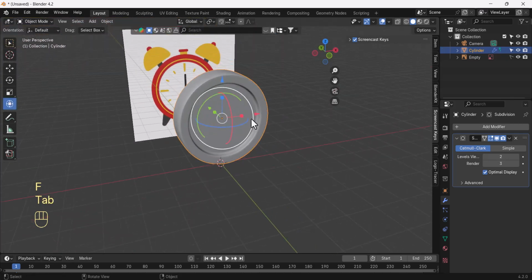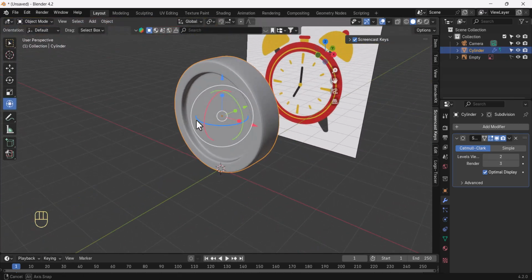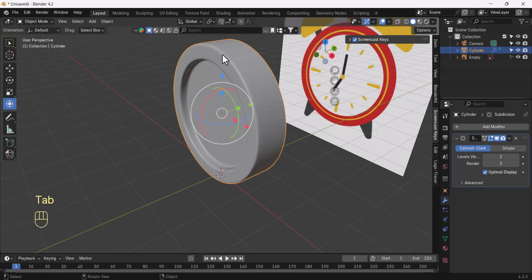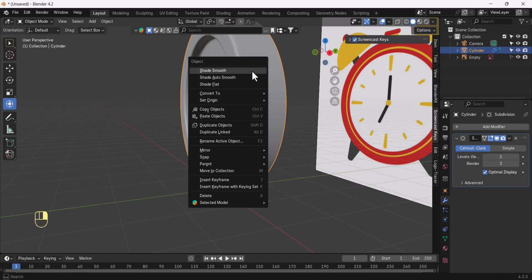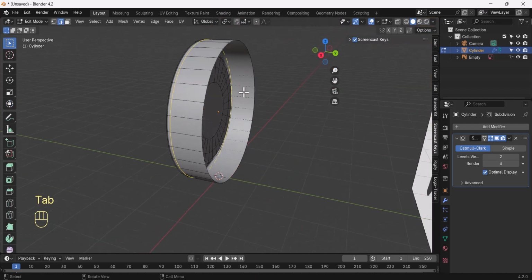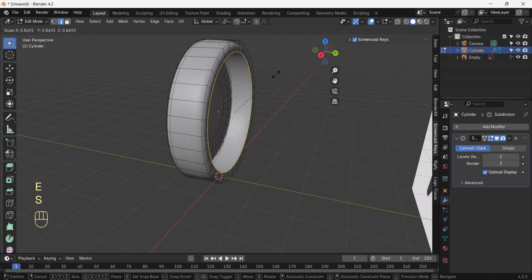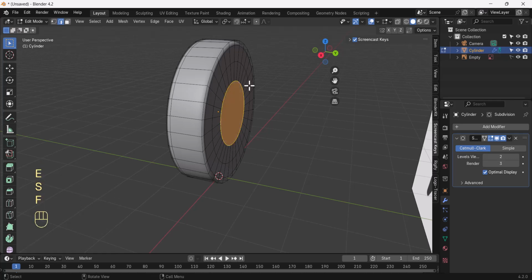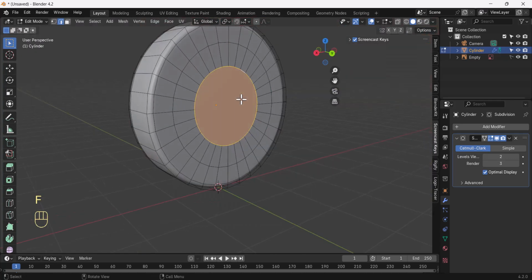Okay, so this is our simple shape, we just traced it, and then again Control R to add a supporting loop till this point. So basically this one, now we need it in a sharp and smooth shape. So this is the simple shape of this block. For the outer you can select it, E and S, supporting edge till this point, and then E and S, E and S, and we can press fill to use this simple fill,